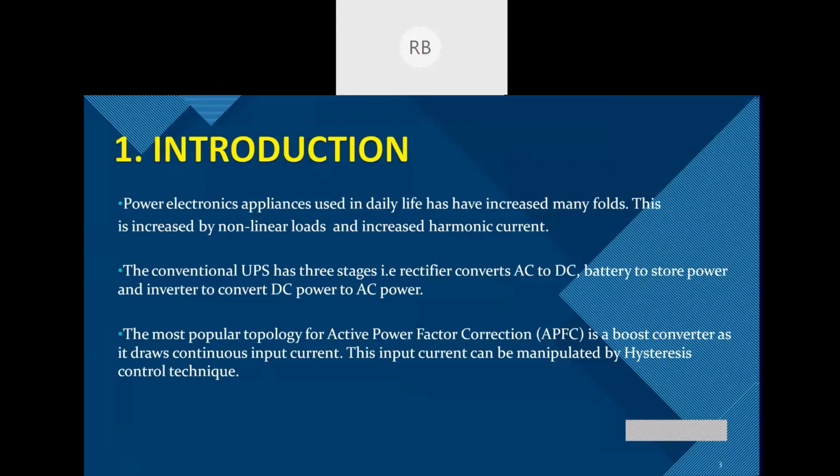As an AC to DC converter, consisting of a line frequency diode bridge rectifier with a large filter capacitor, we use mainly rectifiers to convert from AC to DC, and with those rectifiers we use a filter in order to produce a constant DC output. But the major disadvantage of using this filter is that the input current becomes distorted, and a huge amount of harmonics is inserted.